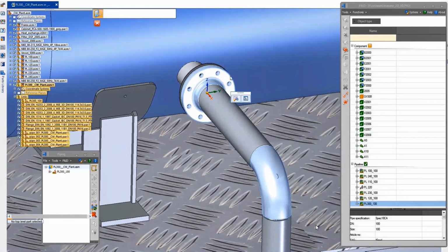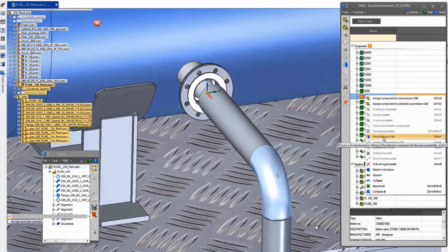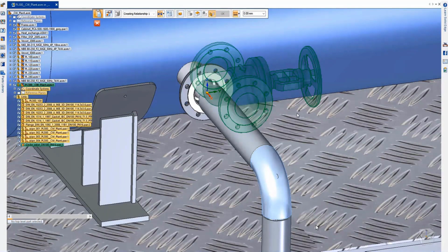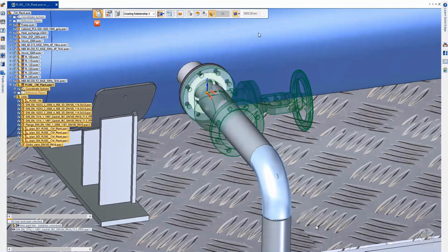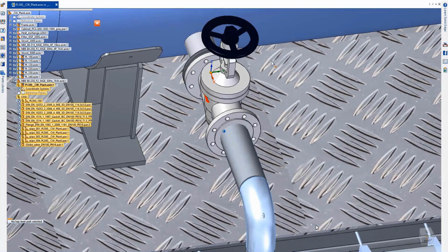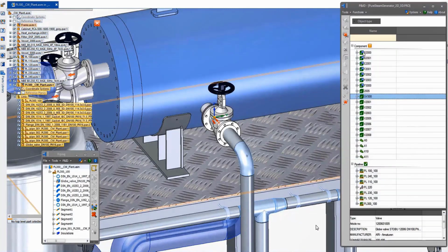When placing components in the assembly, you still use standard assembly placement tools that you already know. So no need to learn anything new to do this. Once placed, a simple recalculation of the route automatically adjusts the pipes and places any additional flanges and gaskets as required. Notice the to-do list shows all the components now up to date, i.e. they're all in green.